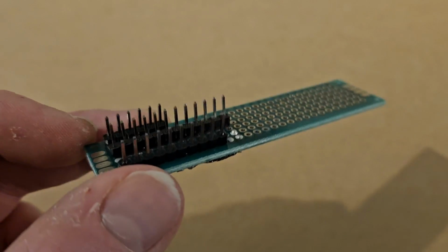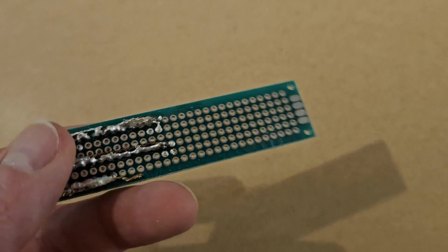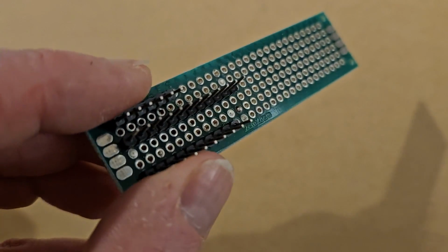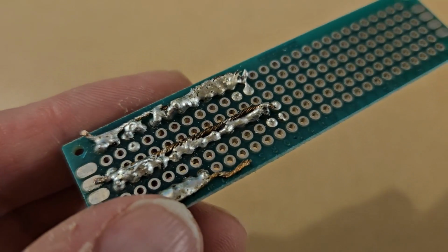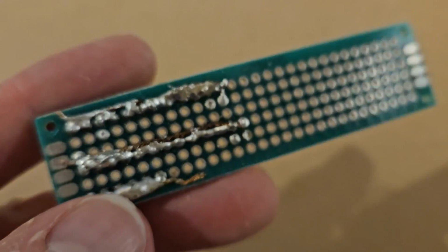And the slightly modified power supply there, and I've made these before. Is this prototype board? I don't quite know what it's called, but just stick a load of pins in, got 3 rows of them in there, then solder them in on the bottom and solder a wire across all of them for continuity. I've continuity tested all of it.